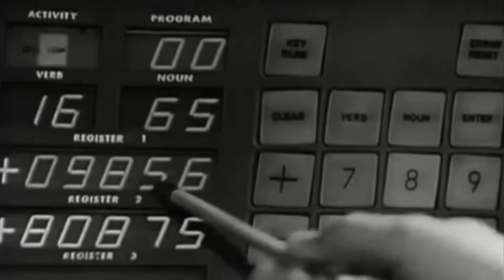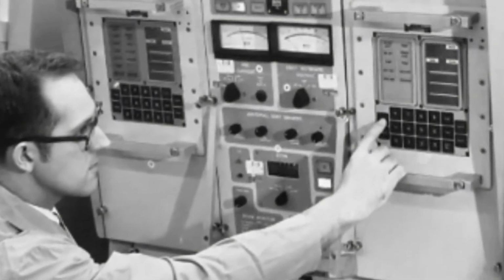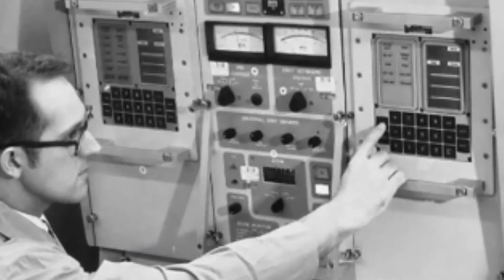The crew interfaced with the AGC using a digital display and keypad known as the DSKY, pronounced disk key, on board both the CM and LM. Mission Control at Houston also had a disk key to interface with the AGC for remote control, if and when necessary. Software for the AGC was written in binary, assembly, or machine language. The interpreter was used to translate mathematical functions, and the executive managed the programs.